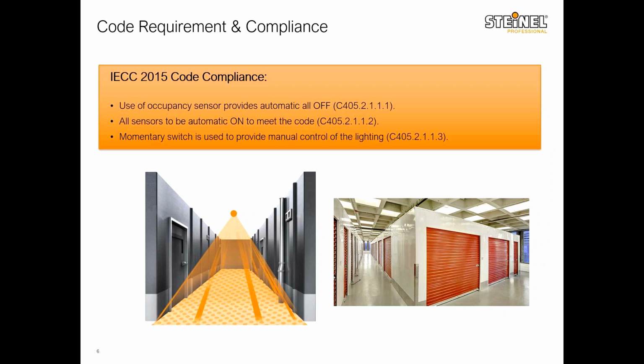And as you can see, you need a PIR sensor. The left image shows it very clearly that you need a sensor that doesn't look in squares or circles, but actually looks up and down the hallway to give you the best performance with the minimum number of sensors.